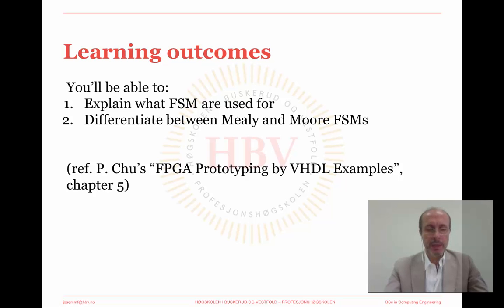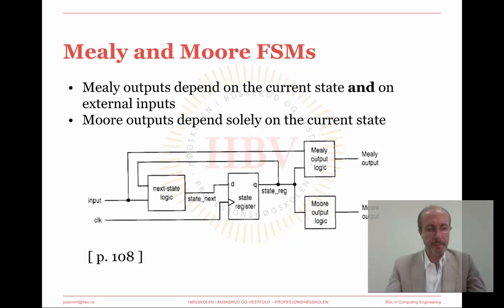And for that reason, the next state logic in finite state machines is designed specifically for each case, following a design method that usually starts by drawing the state transition diagram, which defines the behavior of the finite state machine. But let us start by the basics, which in this case consist of distinguishing between the 2 main types of finite state machines called Mealy and Moore machines.